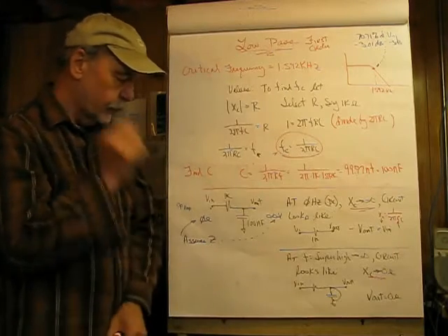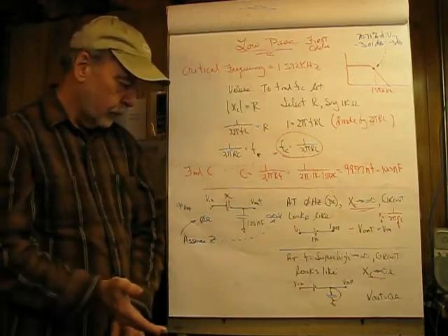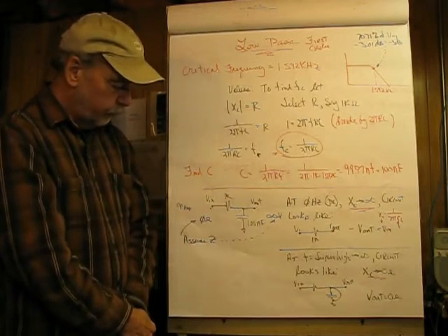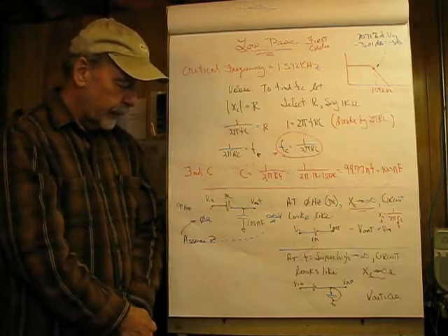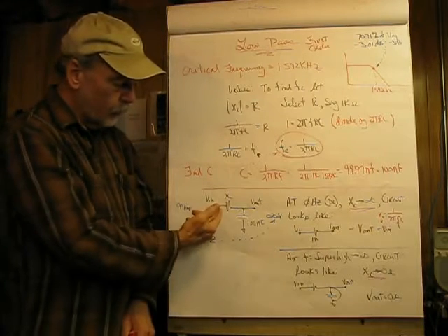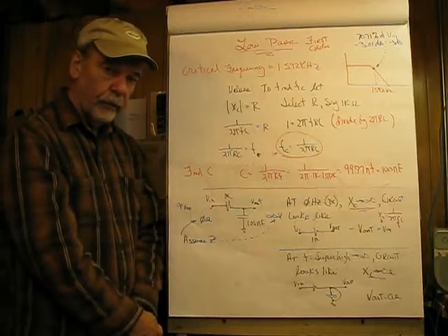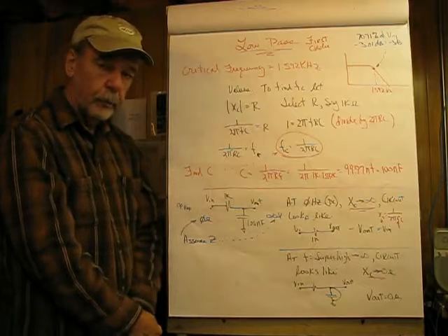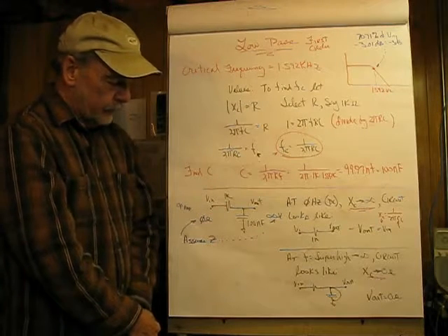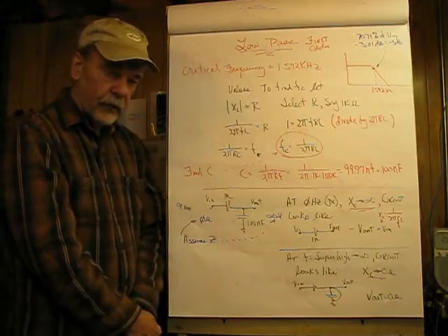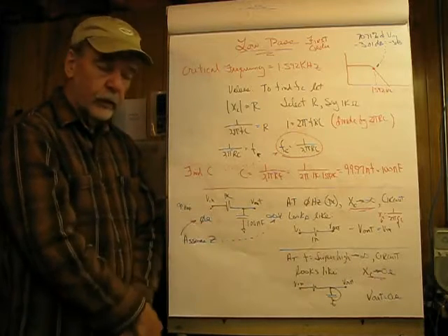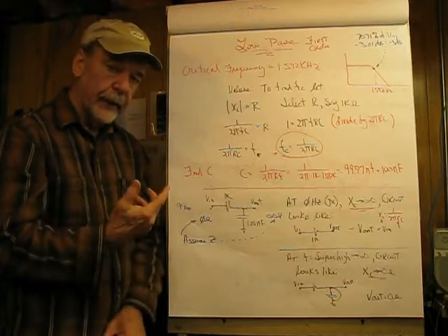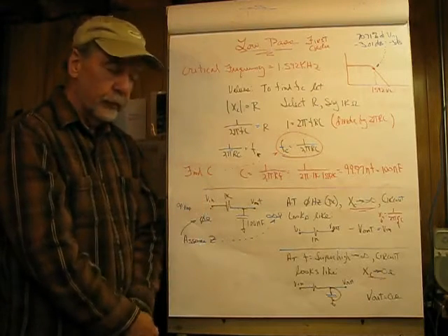So here we have our circuit, and one of the things we have to be very careful of is to take note of what the driving impedance is. Now, for example, a generator typically has a 50 ohm output, so our resistor in series here would really be 1050 ohms, and that's going to affect to some degree the output of this, and considering that to be insignificant. If this is driven by an operational amplifier whose output impedance is really, really low because of the feedback, it is just considered to be 0 ohms.